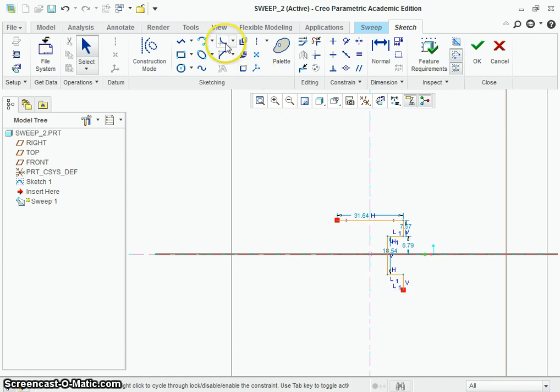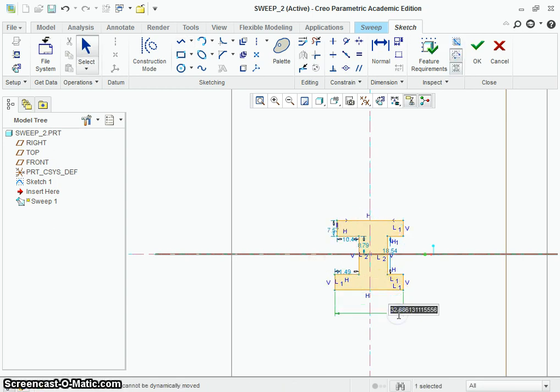Delete that real quick. If we wanted these two here to be different, and it's actually constraining those right now, if you click the right mouse button twice, it will have a line go through it, and that actually will delete the constraint before it's made. And we can go through, and now you can see that those two are actually different.